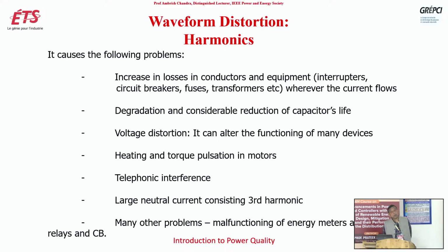And the seventh harmonic is the positive sequence harmonic, so it will generate torque in the same direction as the fundamental frequency is generating, but the frequency is 7 times, so it will rotate 7 times faster than the fundamental frequency which generates the rotating magnetic field.